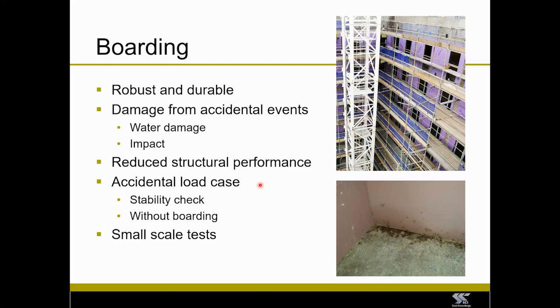But we have said that you should carry out an accidental load case check. So this is designing the structure and the stability system under the accidental load factors, and checking that you still have a stable structure where the contribution from any boarding that would be impaired by an accidental event, which could be flooding, should be neglected.